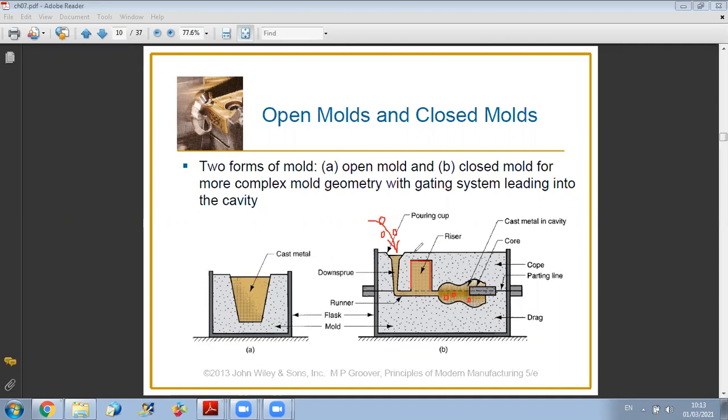How? After the pouring process is over, the riser will allow you to continue to supply molten metal to the main cavity. In this way, it will help in escaping these gases by taking their place. So the first function of the riser is to avoid formation of voids due to gases which are introduced during the pouring process.